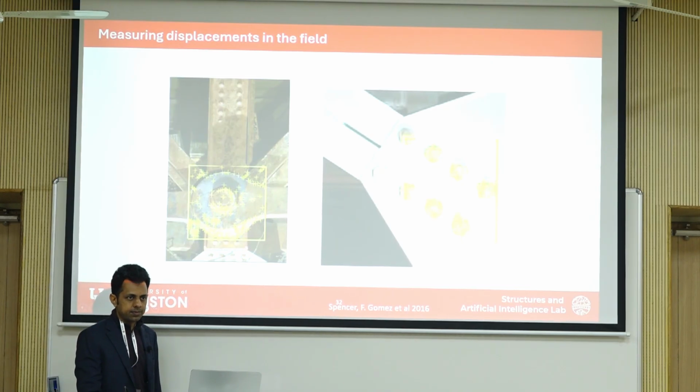Digital image correlation. Yes. Is it a subset of this? Yeah. So it uses optical flow, which is the same method that's being used here. But there, instead of using natural patterns, typically you spray some dots which create that random pattern, and then you can see how those patterns are changing. It's the same principle where you're tracking points of constant intensity across time.